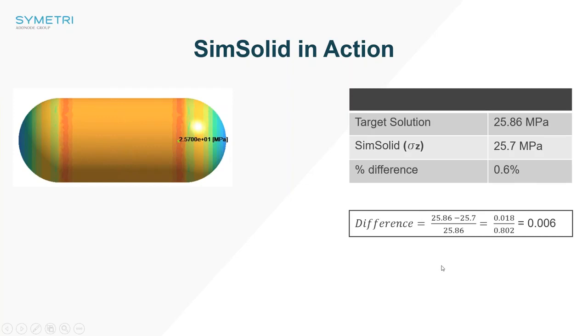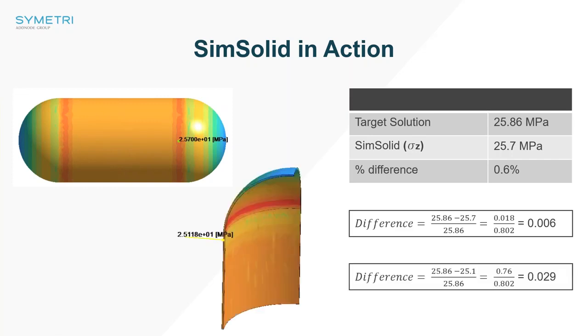Now, if you were to use this because of time, and I'm just not going to use the full model but the quarter model, this is the type of results you will get with the quarter model. And it's slightly higher. It's about 3% difference in results. So both results are acceptable. You can do it either way. I mean, if you want me to show you the quarter model, let me just try that very quickly.